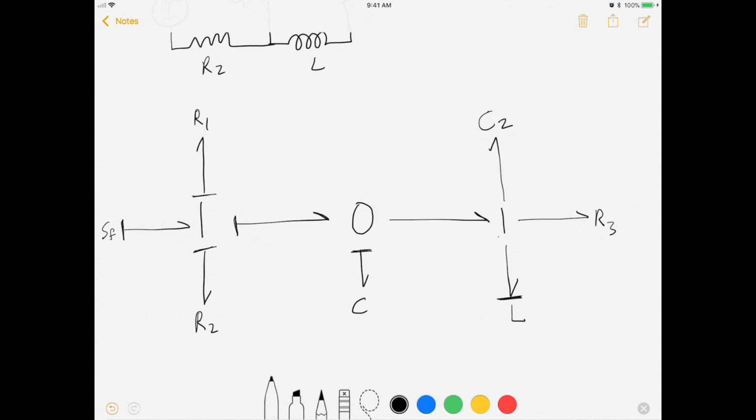There are exceptions to this rule, but for this class in particular, take that to be the rule of thumb, and you will be great. Next, we already have one source of flow into the system. It's going to be this component right here. So everything else has to be an effort, and it is. And there's your causality right there.